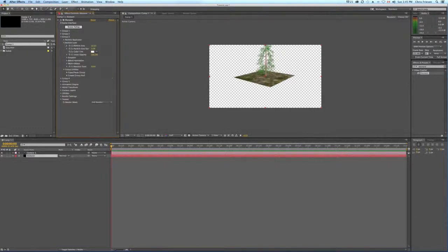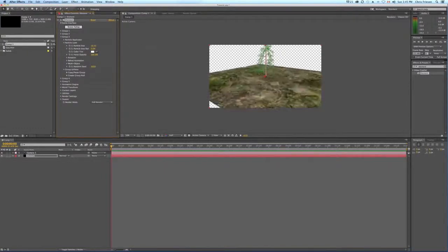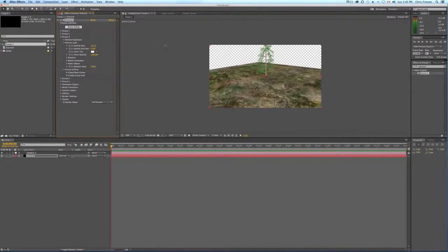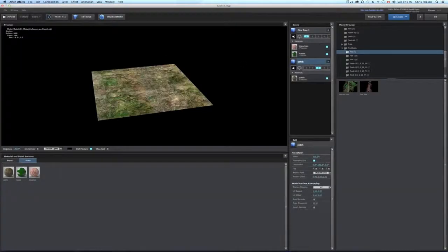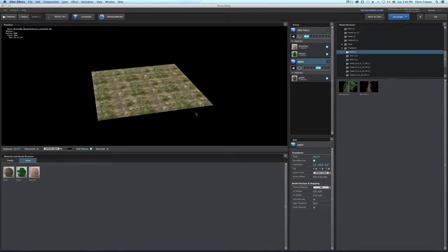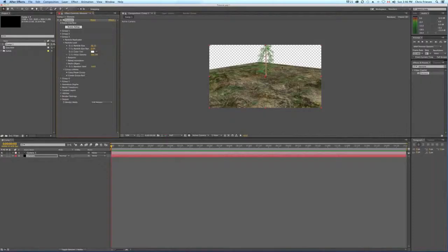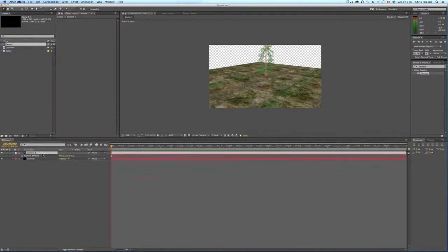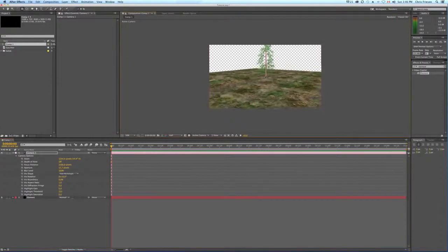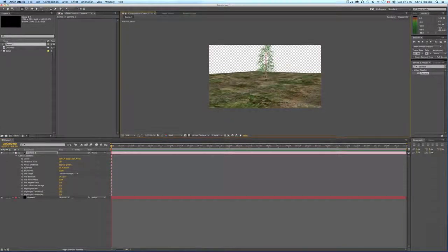I'm going to drop down group 3, go into particle look, and expand the particle size. And since the texture goes up with that, I will go into scene setup, and I'm going to click on patch and increase the UV repeat. That just gives you a little bit of smaller texture pattern. And I'll turn depth of field off on the camera, speed things up.